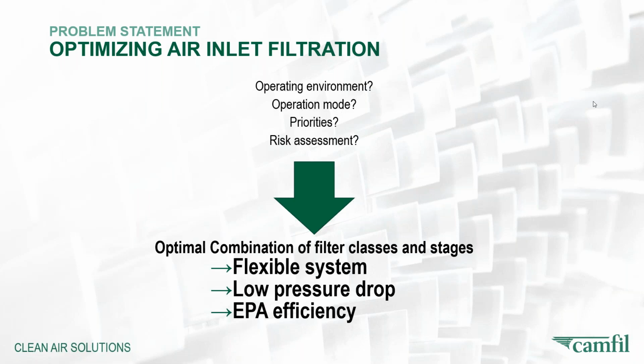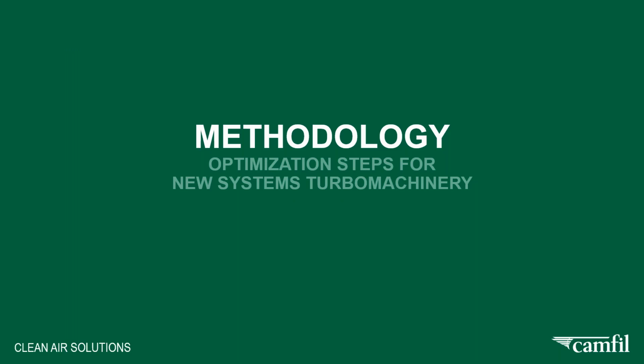And with that kind of information, you need to go to the air inlet filtration experts, and based on that information they will be able to give you an optimal combination of the different filter classes and stages that you need to deliver the performance that you require. Keep in mind that whatever solution you invest in, it needs to be a flexible system. The operating environment as well as your operation mode can shift over time. And furthermore, HEPA efficiency should never be conceded on, because HEPA efficiency is critical for you as an end user to protect your gas turbine from the very first hour that you start up your gas turbine.